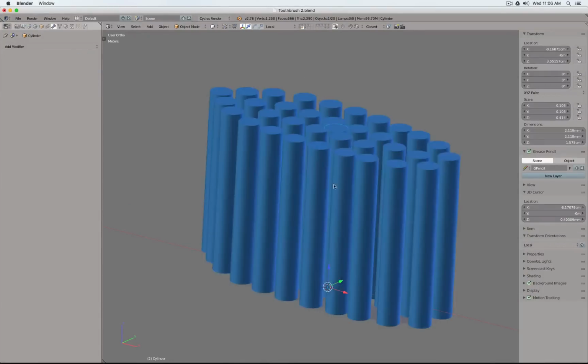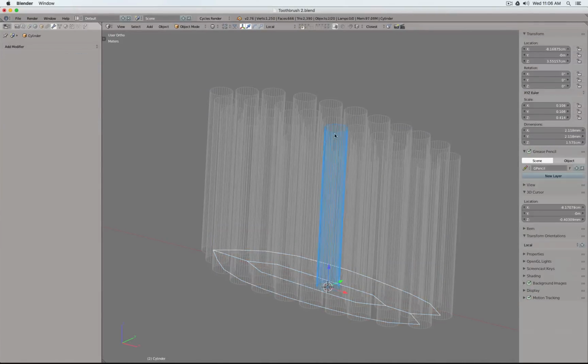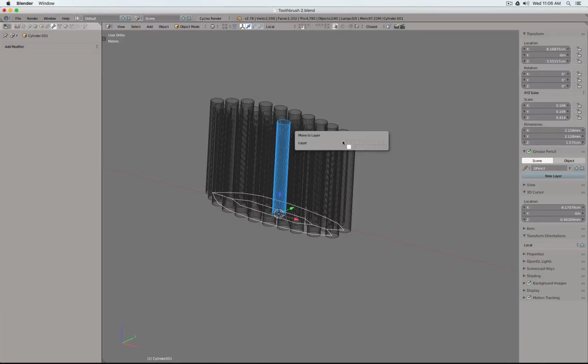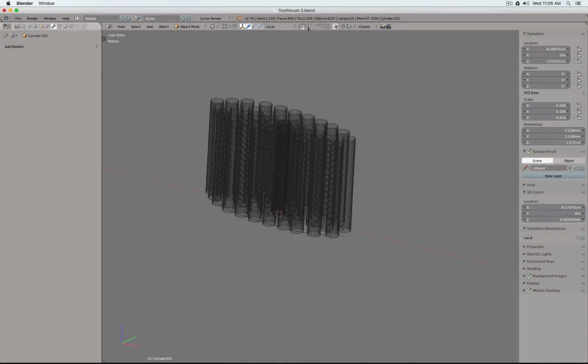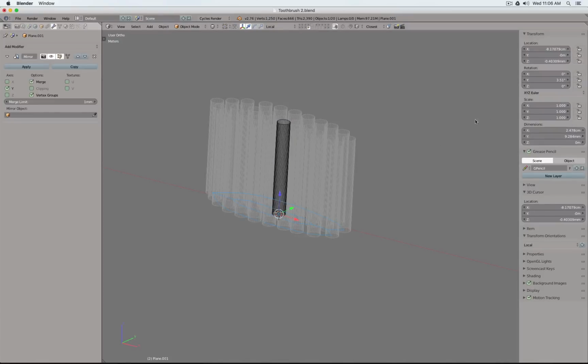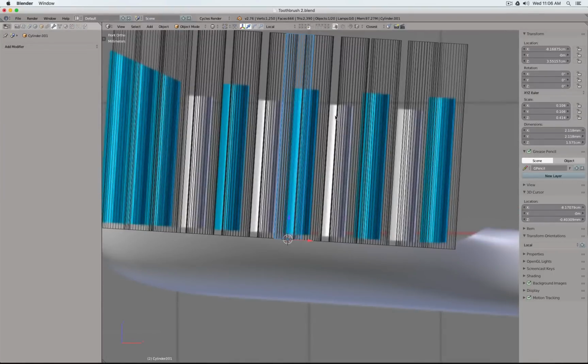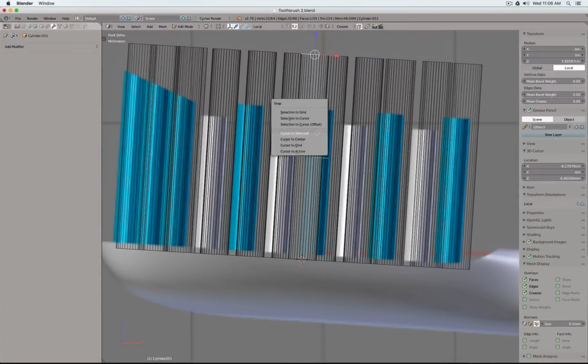So this is, for example, here my masterpiece I started working on, and I will generate now a T-spline appropriate geometry. So I will Shift D and just make a copy, not a clone, and put this maybe onto this layer. And then let's select this part. This is 3.51. Shift S, cursor to selected, go to the cylinder. I will make a copy, Shift D, escape. Let's go back to the cylinder here, and then Shift S, edit mode, Shift S, cursor to selected.